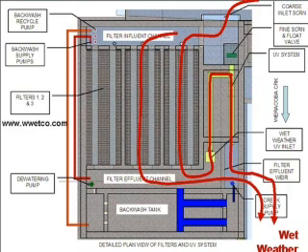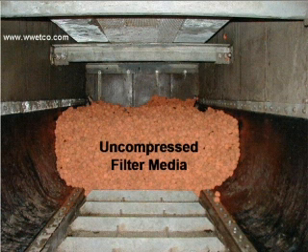So the dry weather flow is pushed through the coarse bar screens and then through a fine screen, and there's a float valve inside the fine screen that will close off the UV chamber once the wet weather occurs. The yellow piping actually houses the UV equipment. It's a medium pressure UV system, and then it exits the end of the piping system. It goes back out into the creek. So the dry weather flow is pushed through to the creek.